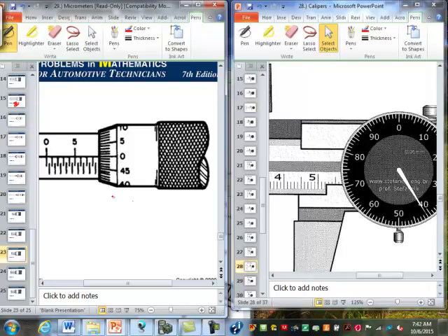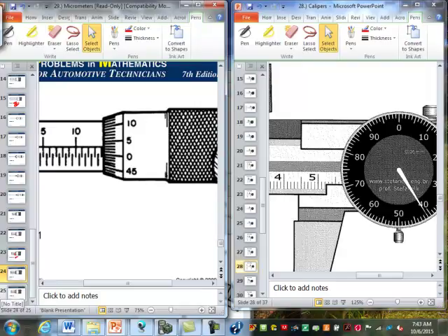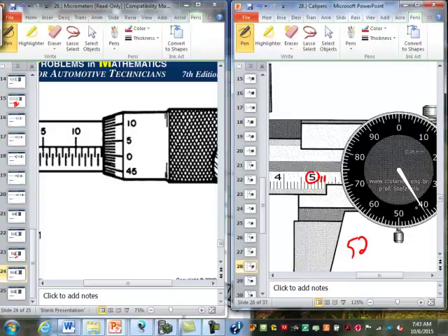So for this one here on the micrometer, what's this one read? Exactly 9. Perfect. Because it's 6, 7, 8, we're past the half mark, but the fact that it's the 0 means it's right on the edge of the next mark, which would be the 9. So what would this one read? Careful. Oops, over here, yeah, this is 52 millimeters. This is 50.41 millimeters. Perfect. So how about back on this one then?